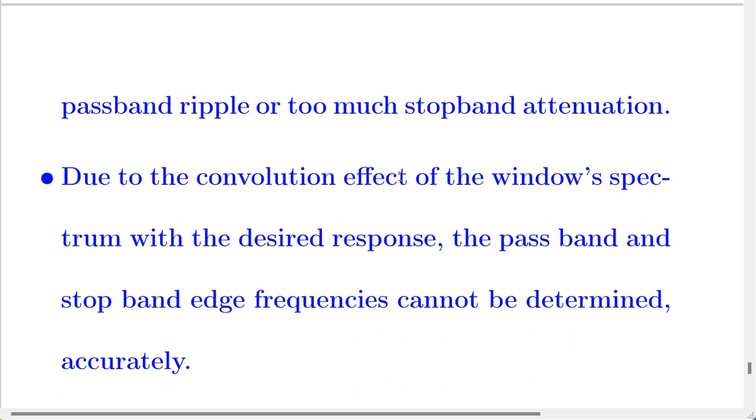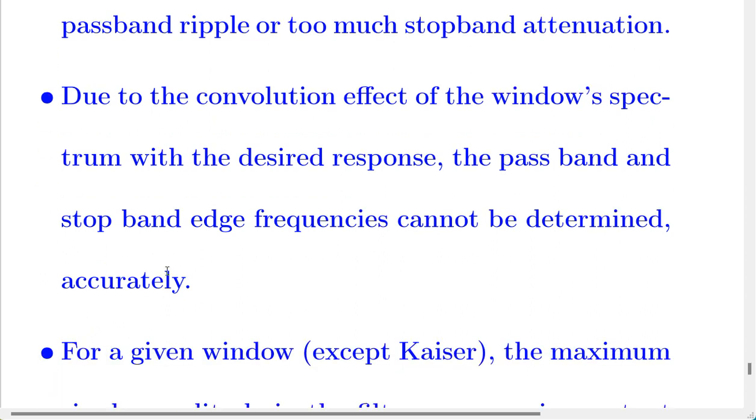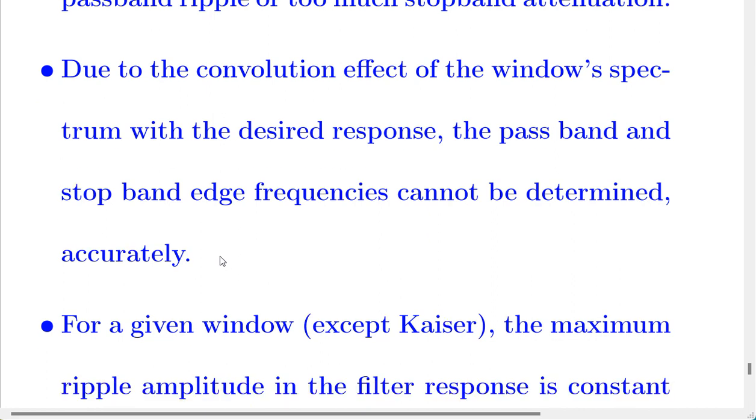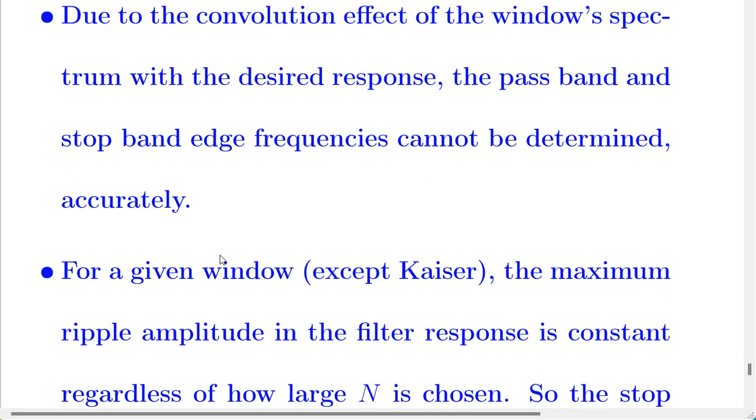Due to the convolution effect of the window's spectrum with the desired response, the passband and stopband edge frequencies cannot be determined accurately. So, this method is under question. Again, cannot be determined exactly and accurately. Can you use it in serious designs? Okay.